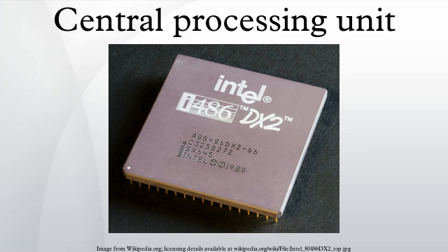Performance. The performance or speed of a processor depends on, among many other factors, the clock rate and the instructions per clock, which together are the factors for the instructions per second that the CPU can perform. Many reported IPS values have represented peak execution rates on artificial instruction sequences with few branches, whereas realistic workloads consist of a mix of instructions and applications, some of which take longer to execute than others.